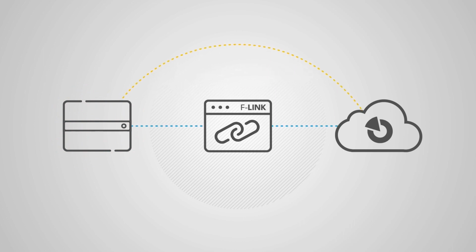According to the installer's rights, which he has in the cloud, F-Link creates a form for registration and pre-fills the data such as serial number, etc. For registration, it receives data from the cloud and sets it in the control panel locally. When the installation is finished, the installer must end service mode and unplug the USB cable for correct downloading of the control panel settings. This registration can be made also remotely by F-Link if persistent communication LAN is set.